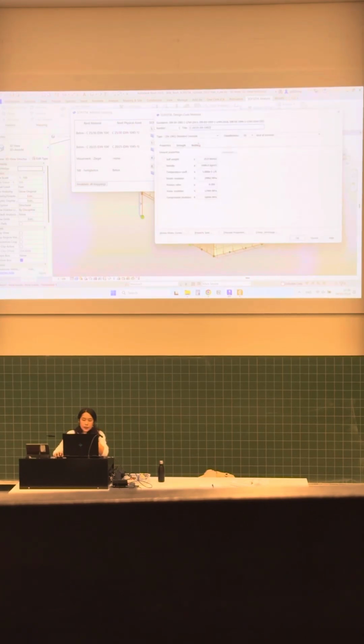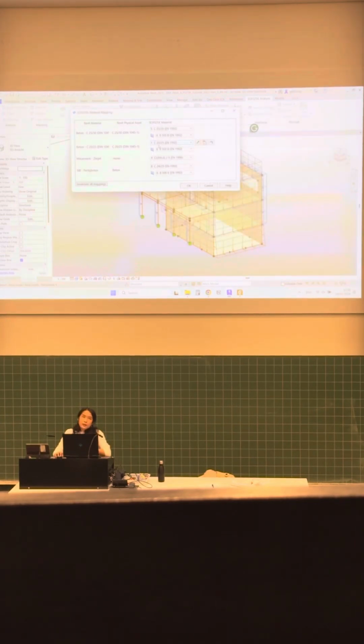And again, you can edit it in case you have, for example, a recycled special material that has different properties which are important for the analysis. It's also a hack in case you want to change a material in the future, for example, upgrade all the concrete in the model to C20/25 or C30/37. You can just do it from here. It's a bit faster way to change it, and it will basically read this information further.